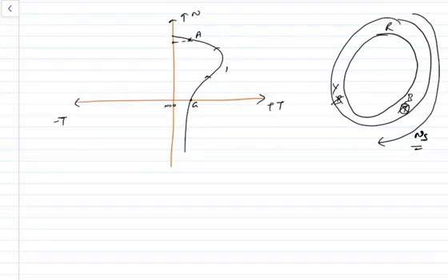So now we know a rotating magnetic field always comes from R to Y to B, so it will start rotating in this direction. You can see here now NS is changed. That means the direction of the rotating magnetic field is now becoming opposite. When the direction of the rotating magnetic field becomes opposite, then the characteristic also will flip. That means the positive speed now becomes a negative speed.